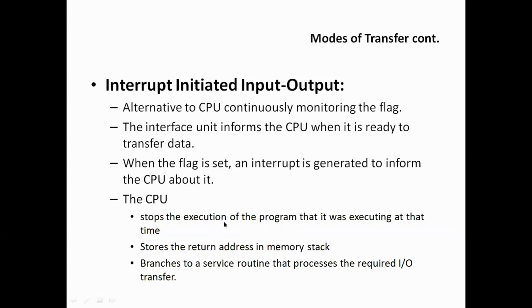Before leaving the current thing and going to a new thing, the computer will store the address of the next thing onto the stack. The address of the next instruction will be in the PC, the program counter. That program counter content will be stored onto a stack. I am simplifying things here.